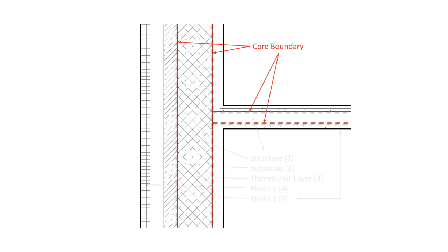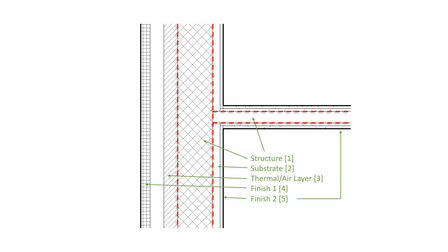The layers are also assigned a function and priority which will influence the cleanup too. There are 5 functions with their associated priority shown in parentheses, with priority 1 being the most important and therefore priority 5 being the least important. The function indicates what the layer may be used for, but when walls join, it is the priority which controls the cleanup.